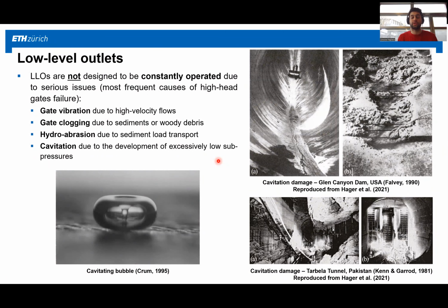to severe issues that they can face. And some of those are gate vibration, which are due to the high-speed flows, gate clogging due to debris, which can be sediments or wood debris, but also hydroabrasion and cavitation.